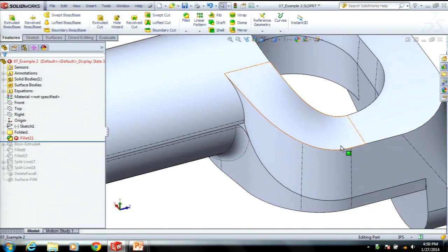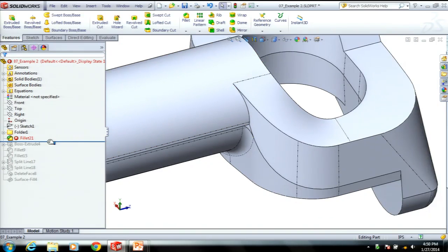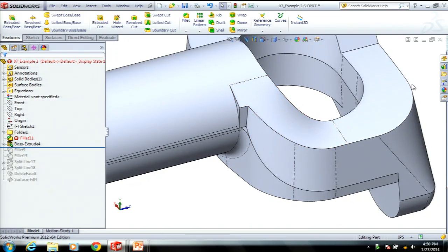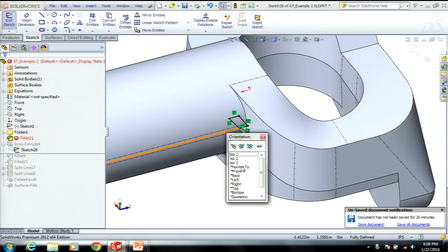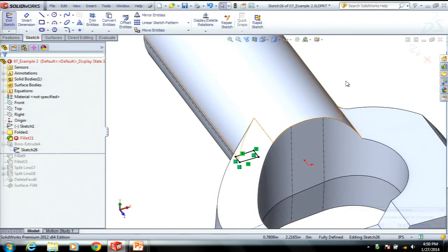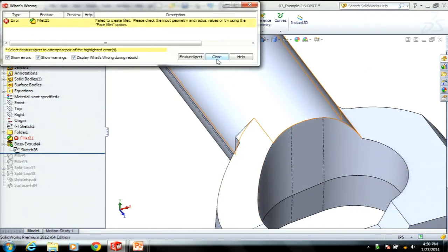And I'm going to add this fillet and then manually build this little corner here so I don't have the sliver face. So just like we cut away a portion of the model in the first example, I can extrude a block into the model to help end this fillet. Now when I apply the fillet along this set of edges here, it can cleanly stop at this planar face. What my sketch looks like is just some lines made coincident to vertices in the model.